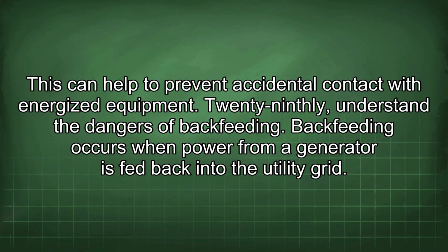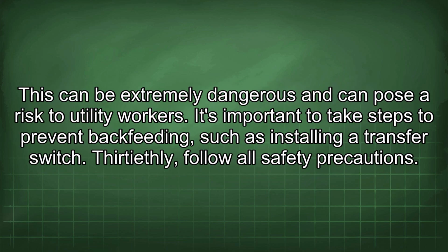29thly, understand the dangers of backfeeding. Backfeeding occurs when power from a generator is fed back into the utility grid. This can be extremely dangerous and can pose a risk to utility workers. It's important to take steps to prevent backfeeding, such as installing a transfer switch.